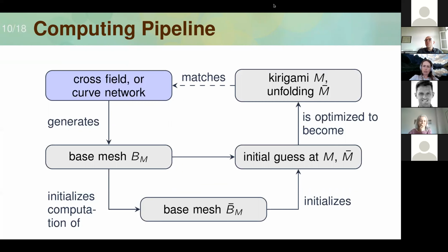And this you can throw to the optimization now. So we have hard constraints, that is equality of many edge lengths. And we have soft optimization targets, that is energy functionals that penalize the sum of squares of second differences. So those energy functionals are small if the resulting structure is fair.